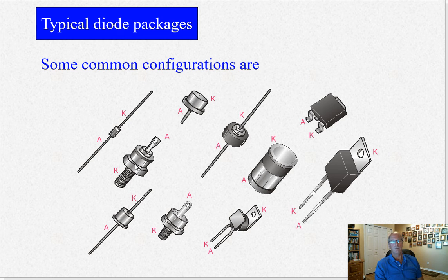Okay. The power in a diode, remember power is voltage times current. What's the voltage in a diode? 0.7 volts, right? Multiply that times the current going through it. That's the power in the diode. So this diode here with a metal thread and stud, and this one here too, which has a little tab, is a TO-220 package, which allows it to be mechanically anchored to a heat sink, so it can dissipate lots of heat and a lot of power. So there's a lot of current going through these diodes, used for power supply applications.